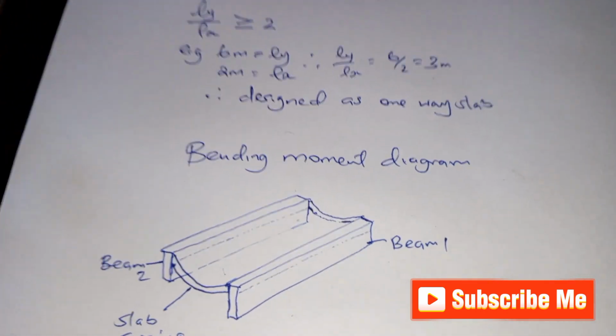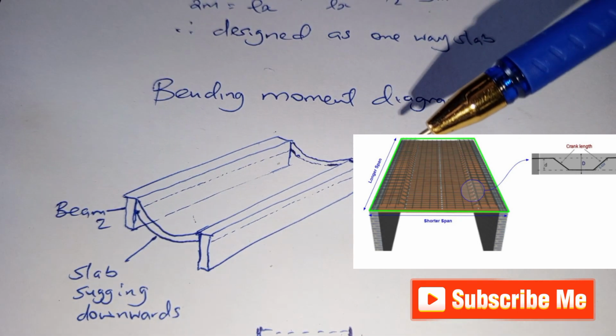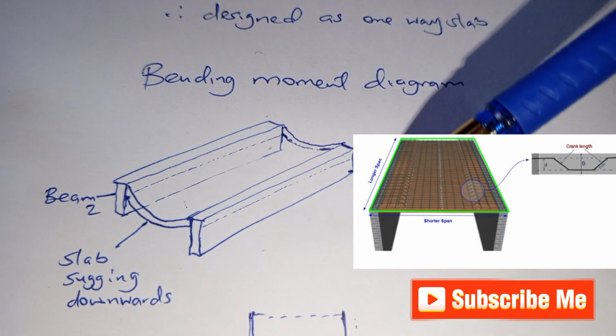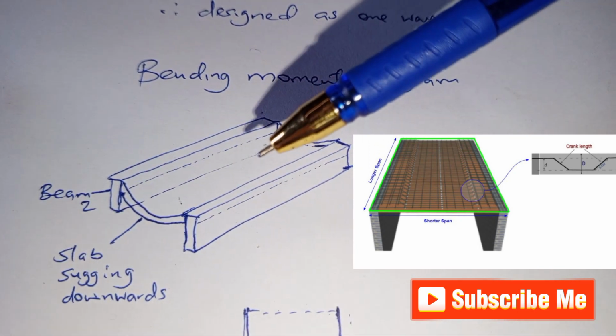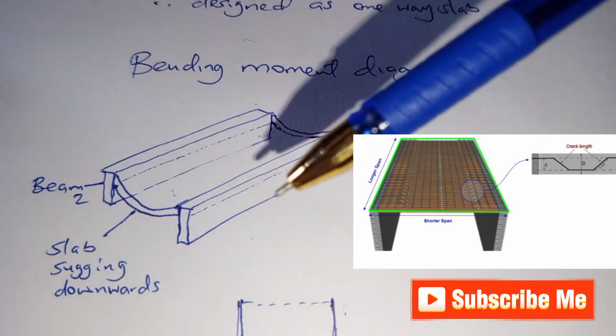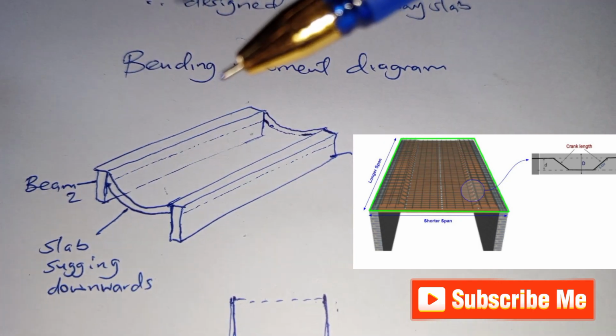For a one-way spanning slab, it is supported on two sides. For example, in our illustration here, we have beam 1 and beam 2, and in between is the suspended slab. So this suspended slab is being supported on two sides. That is a one-way spanning slab.